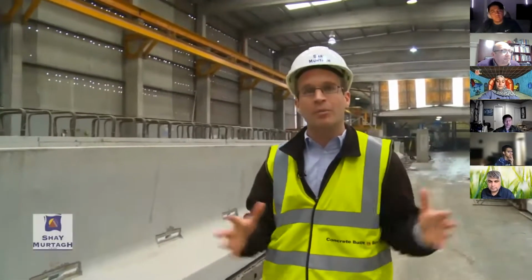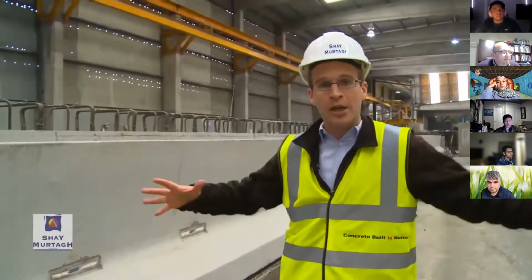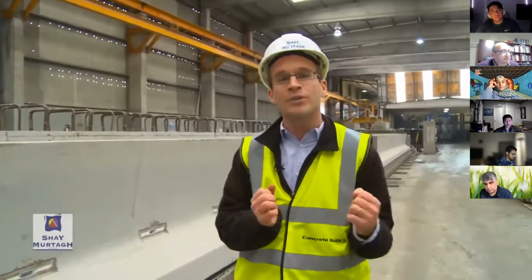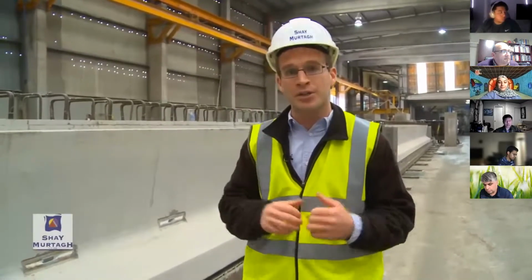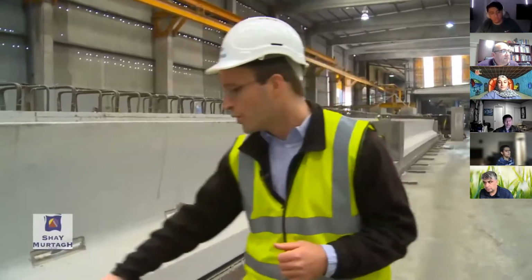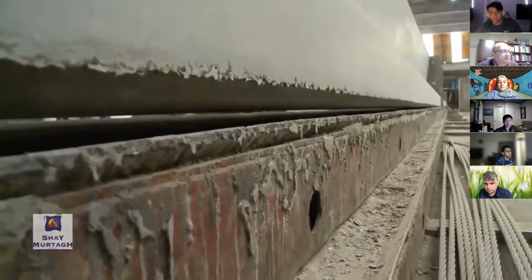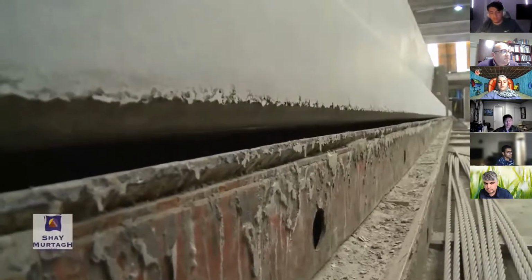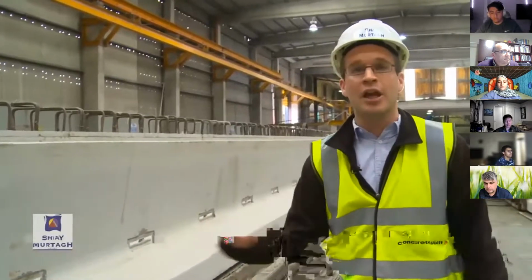When we apply that compressive force from the pre-stressing tendons, pre-stressing strands, not only do they apply that beneficial compressive force to the beam, but they also apply a moment that relieves the moment applied under working conditions. So this moment applied by the pre-stressing operation results in the beams actually cambering up. The beam will lift up several millimeters, 10 millimeters, whatever the case may be, depending upon the beam and the pre-stressing amount and layout used. It will actually camber up.